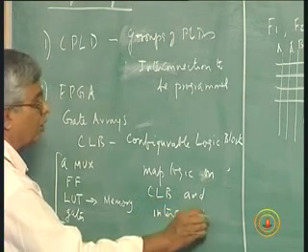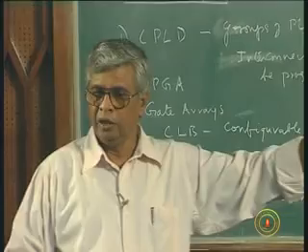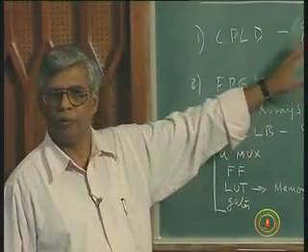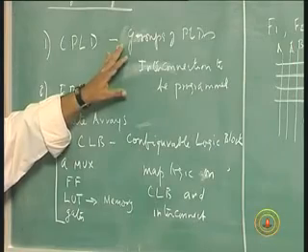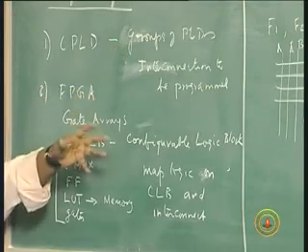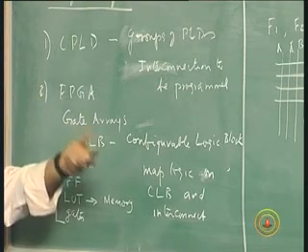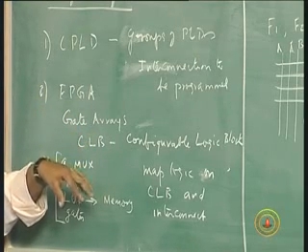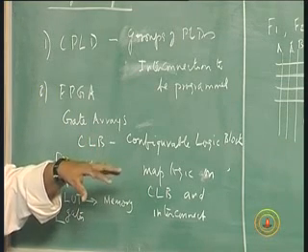That is the difference between these two. Here there are the standard PLDs which we are familiar with. There is a switch matrix. You program for switching them properly, connecting them properly. You program only the interconnects. Here I have to map my logic. I have to break my logic into efficient blocks which can be fitted to each of these CLBs. And then not only do you have to map them efficiently, you have to interconnect them efficiently.